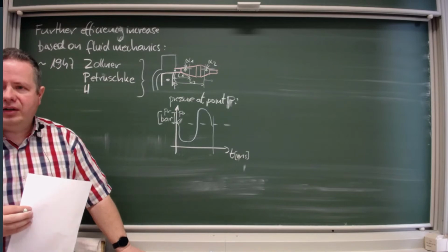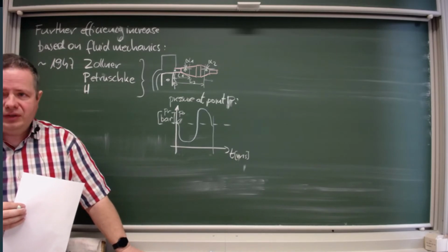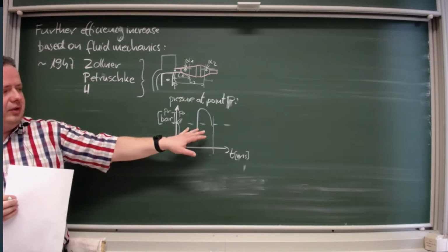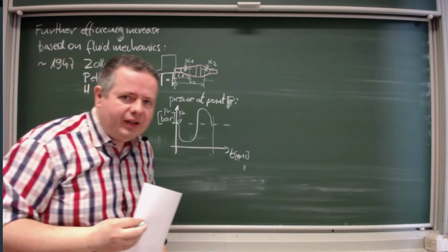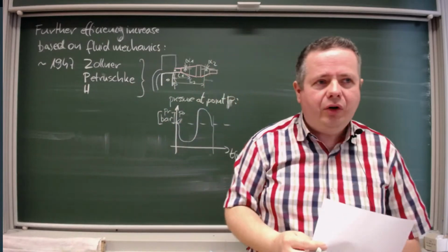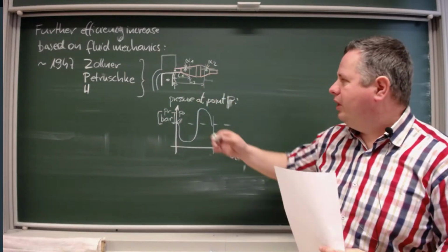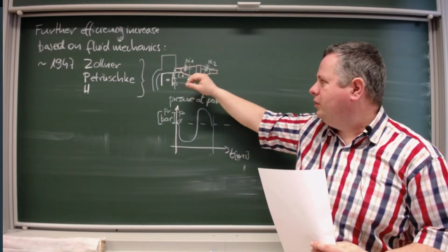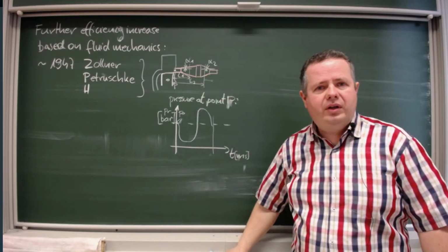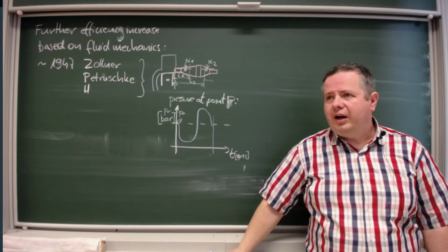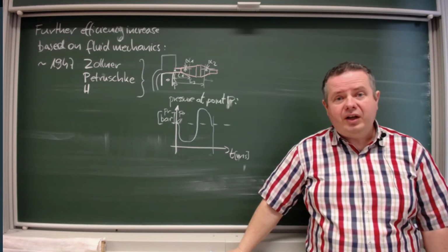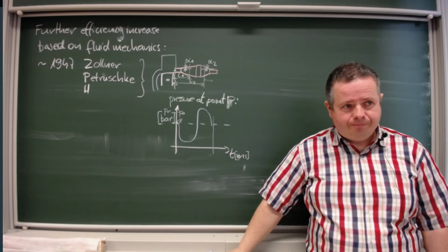These two angles and two distances describe this pressure variation. And again, you can have an ideal tuning of the system. You can choose your diffuser and confuser in such a way that you get a considerably large power peak at a given RPM domain. Okay?